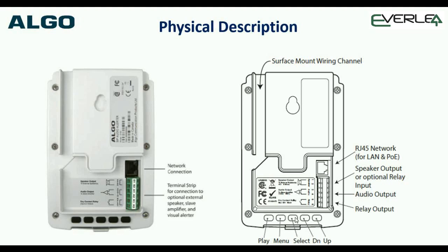So from a technician's perspective, you plug it in, you mount it, get the IP address, walk away down to your laptop. You can program it. You can test the ringing, you can test the page, set everything all up, all via the browser, whilst you're in the room if you've got a wireless connection. So a nice, easy unit to install and use.